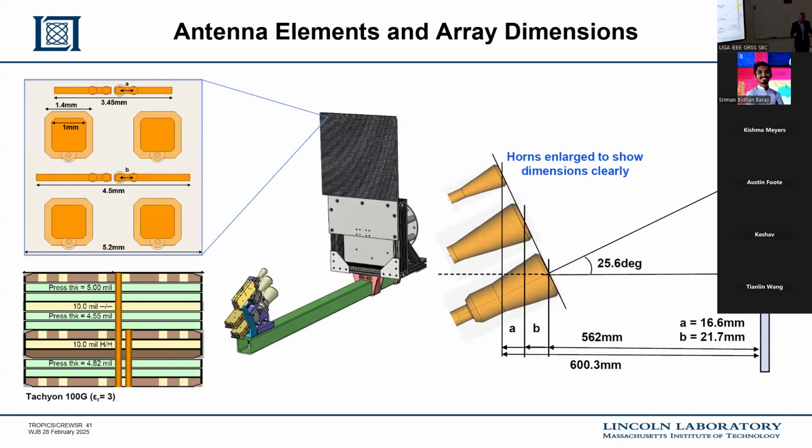Okay. A few more details. I think we have some antenna guys in the room here, so maybe this will resonate with you. No pun intended. All right. So each one of these is 5 millimeters on the side, right? Very tiny unit cells. And in each one of these cells, there are 4 antennas at 58 gigahertz, 1 at 23, and 1 at 31. And each one of those patches on the other side of the array is connected to an RFIC that introduces a phase shift. So there are hundreds of thousands of these antennas on one side and RFICs on the other side.